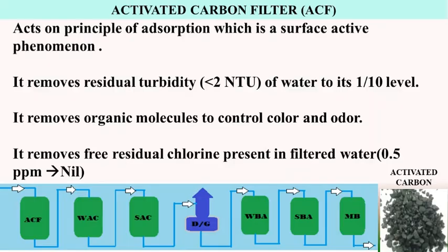The adsorption process in the system is introduced by activated carbon, alumina and silica gel. A number of solid adsorbents diffuse on the surface of the solid adsorbents. Organic chemicals imparting color, odor, taste, heavy metals, fluorides, all are removed by this adsorption process. Large surface area accumulates more ions, and adsorption capacity depends upon the solvent-solute-solid system.